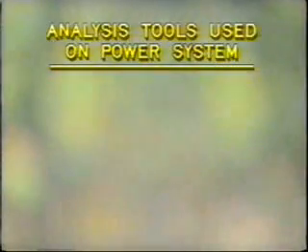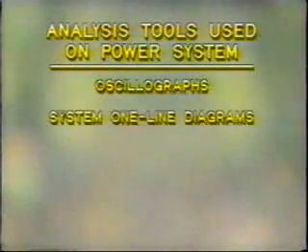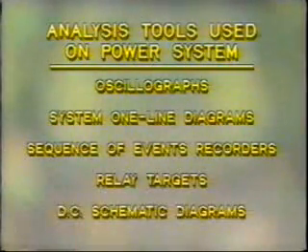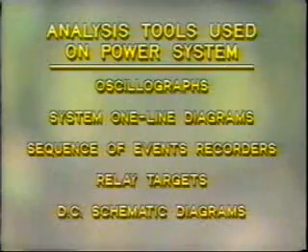In this segment, we'll be looking at the most common analysis tools which are used to investigate faults and other disturbances on the power system. These are oscillographs, system one-line diagrams, sequence of events recorders, relay targets, and DC schematic diagrams.